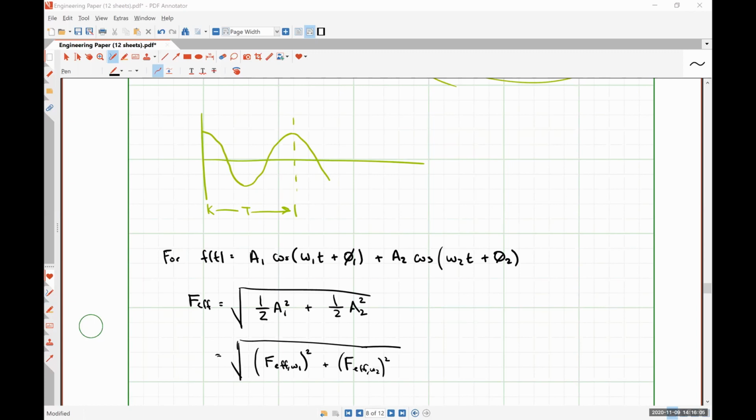Problem 3, you're asked for the complex power. Notice again, you are not given an RMS value, so you need to convert. Problem 4, same deal. You're not given an RMS value, so you need to convert before you can do any of that stuff. Problem 5, you're finally given RMS values, and it's easy street.